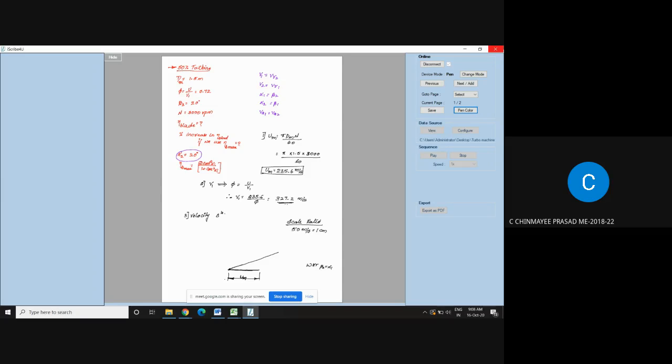So should this triangle be taken vertically or horizontally? Yeah, you can take it horizontally, no problem. Like the same as the De Laval turbine, you can accommodate. There I am showing, like that only we take, no issue. So here this will be V1. V1 we got, what should be the length of V1 as per the scale ratio? 327.25. As per my scale ratio, it is 6 centimeters only. So I have drawn a 6 centimeter line and I have joined it.